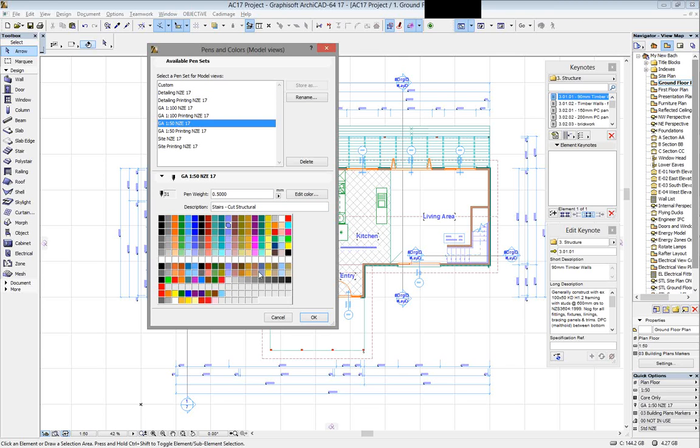Jonny talked about this next row, the dual row of pens here. These are the brand new building material pens for ArchiCAD 17. This is the change between the 16 and 17 pen sets, the addition of these two extra lines, which unfortunately has meant all our New Zealand pens, these bottom 4 rows here, had to move down 2 rows, which is going to cause a lot of problems if you want to copy and paste a detail from version 16 to 17, because if you used these detailing pens in version 16, they were up at this row here.